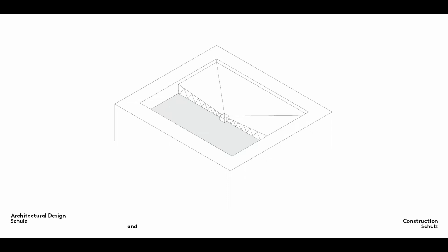The shape of the insulating panels required depends on the position of the roof drain, which should be located at the lowest point of the roof. If the drain is sited in the center of the roof and the insulating layer slopes outwards at an angle of at least 2%, then the highest point of the roof lies at the upstand.